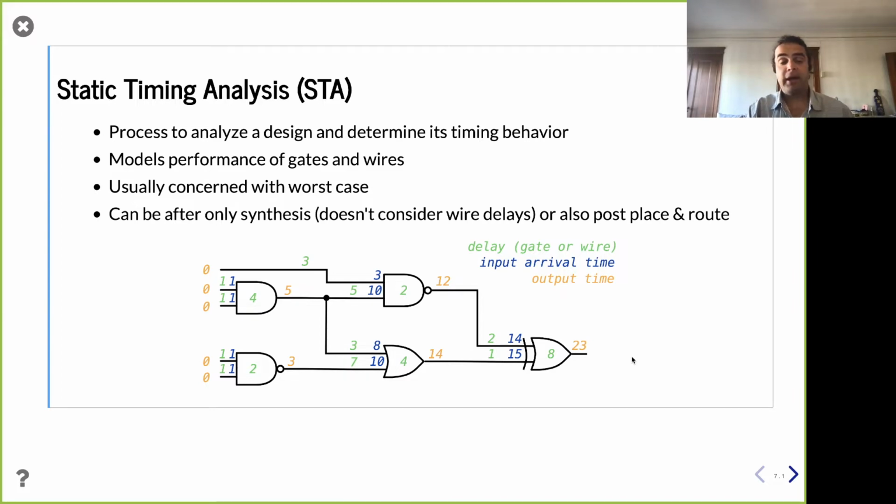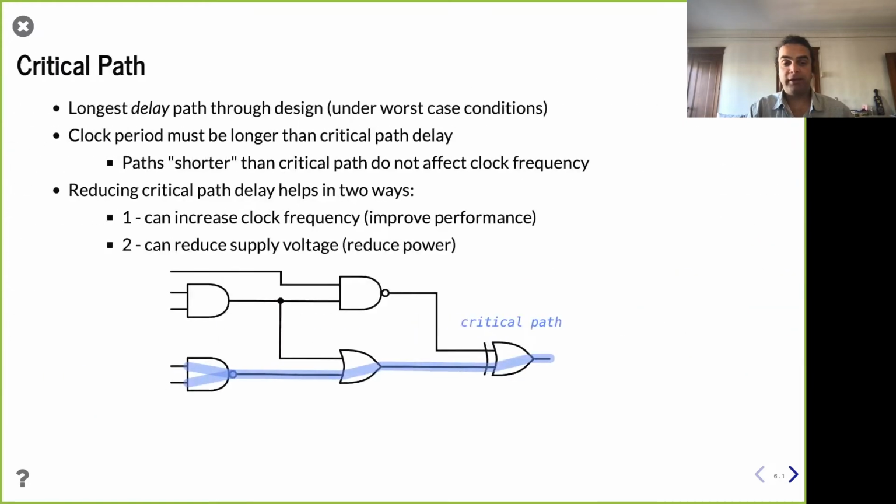To actually find a critical path, now we need to crawl backwards, right? So crawling backwards, at each step of the way, we're going to find the last arriving thing. Okay, so this one arrived at time 14, this one arrived at time 15. This is faster on a critical path, so this actually doesn't matter. So we take the longer delay one, get here, see which one was later arriving, this one was later arriving, we get here, and then these two arrive at the same time, so they're both critical path, right? So actually, if we go back a slide, you can see that they both are.